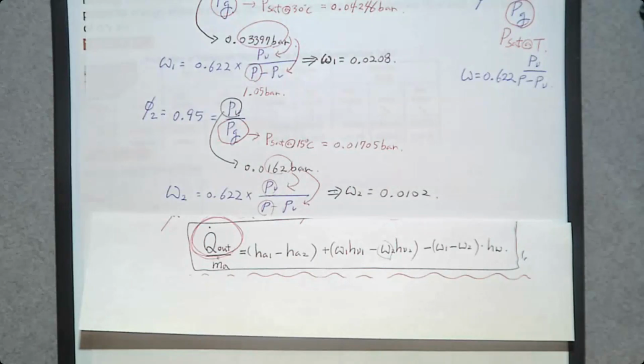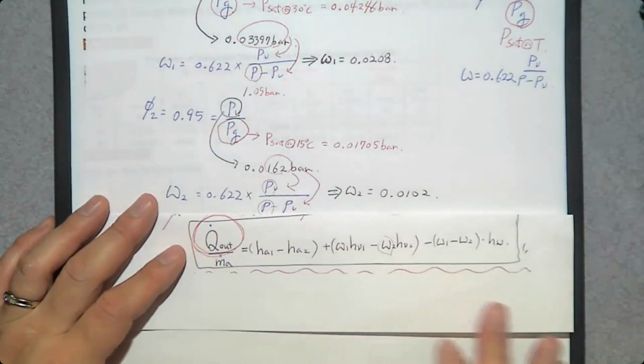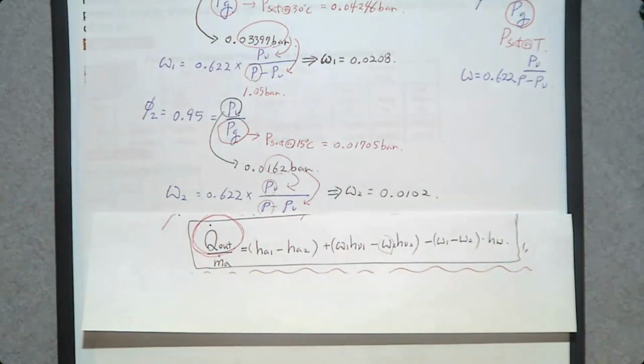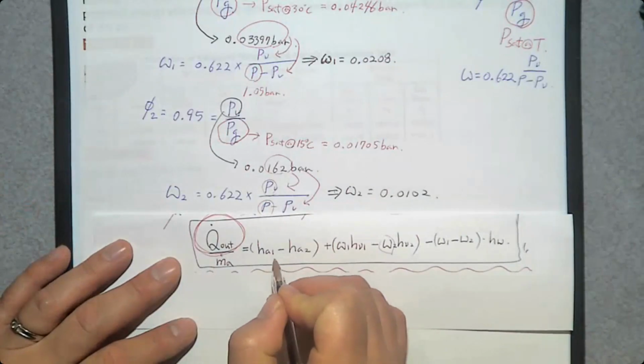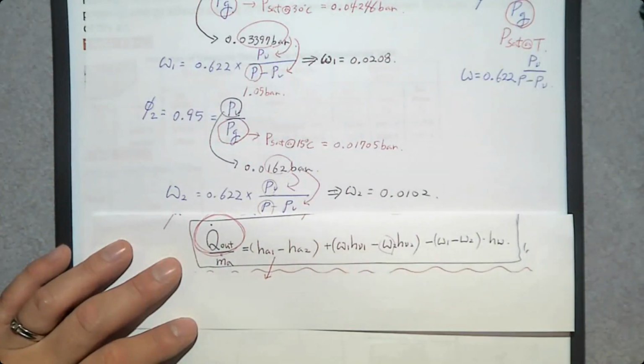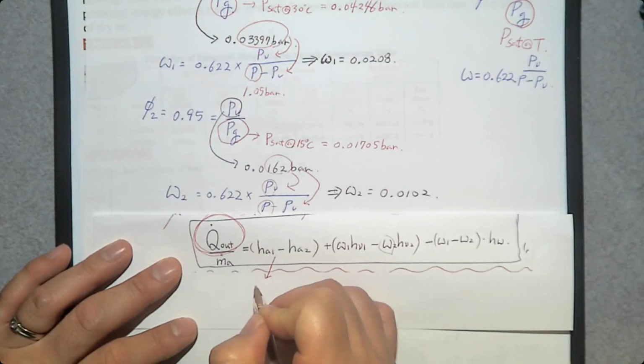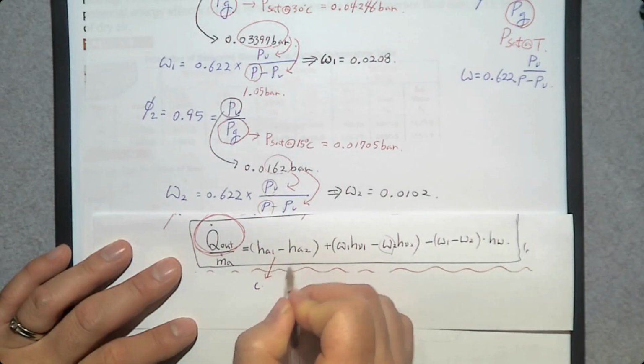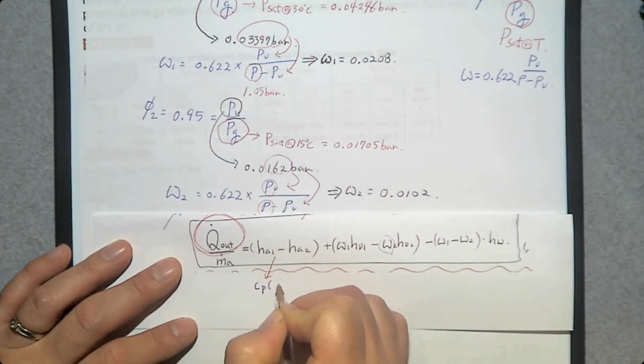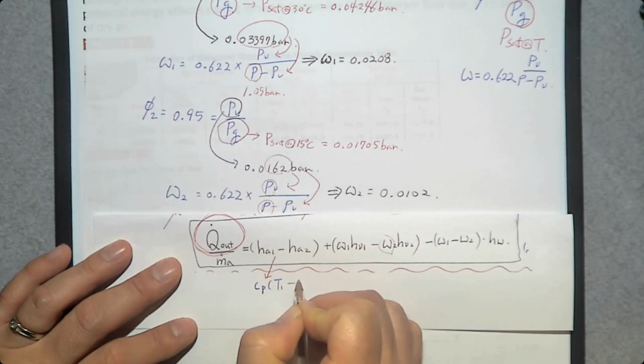There's no problem. But because last time we used the ideal gas property table in the previous problem, this time we can use specific heat, so you can experience both methods. So h1 minus h2 is Cp times T1 minus T2.